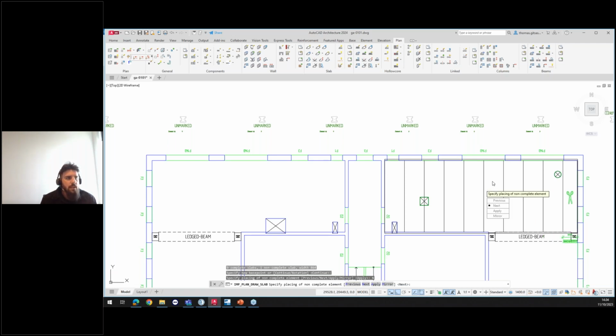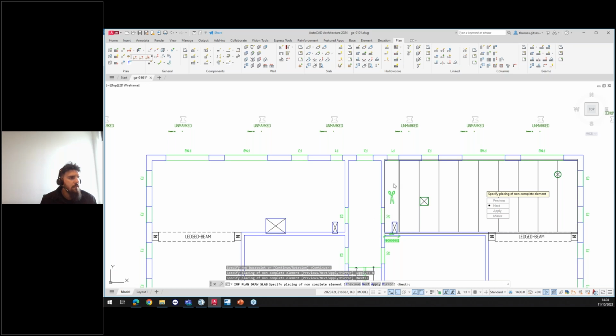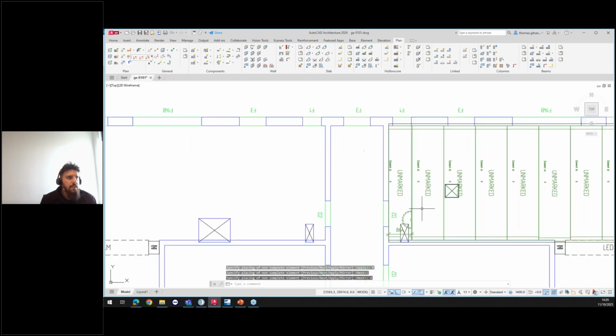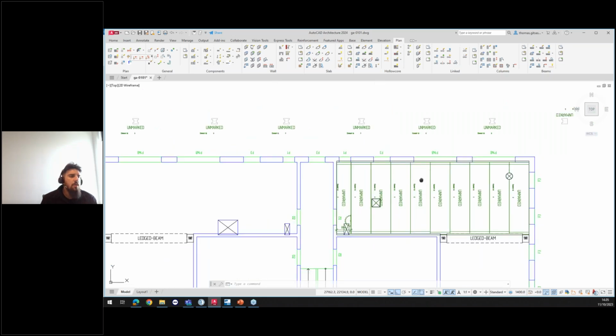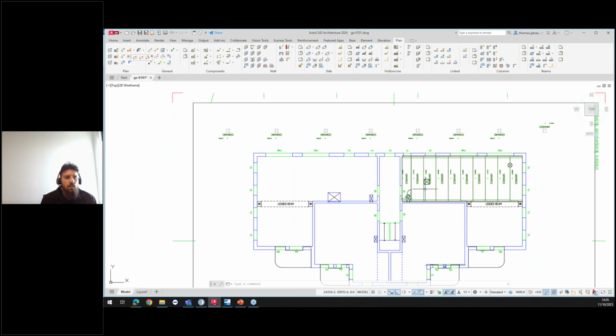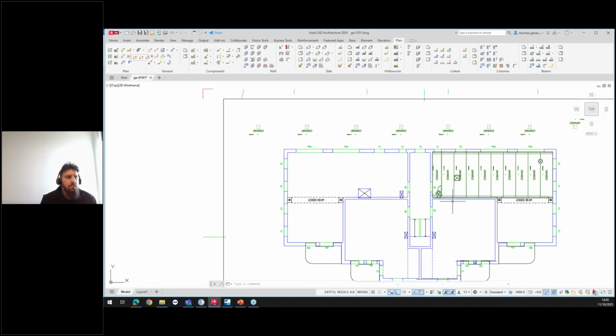I can say next, and then next, and then the cut slab is basically here at the end, and this is what I want to do. So I will say apply, and that's basically it. Now I have created a slab here with a hole, automatically defined circular hole between those two slabs, already defined, and part of my floor is being done.